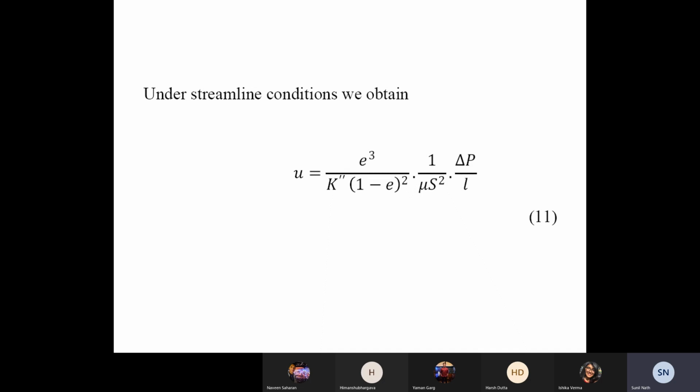So what we have done today is we have derived the same equation that we obtained by other sundry approaches, a more ad hoc approach a couple classes ago, and I have used a similar force balance type approach, and by balancing the pressure drop across the free cross section of the bed, we have derived an equation for the regime of modified drag coefficient versus modified Reynolds number, which is called Karman's graph, and I can use that to find velocity, or better still, generally it is used to calculate the pressure drop across packed beds.